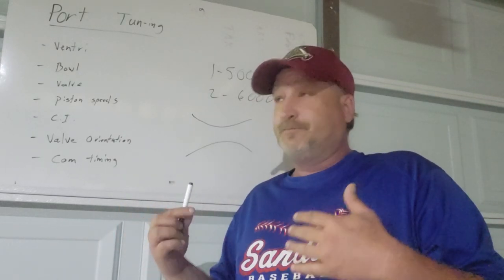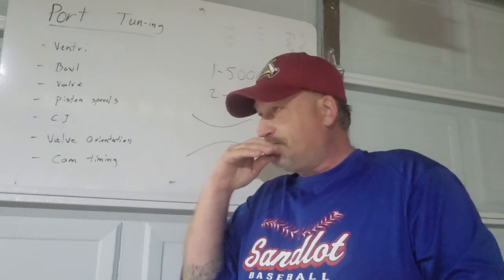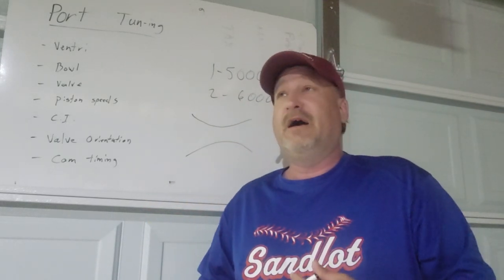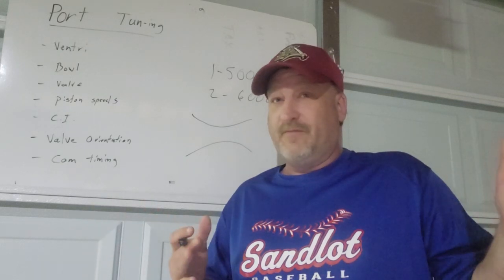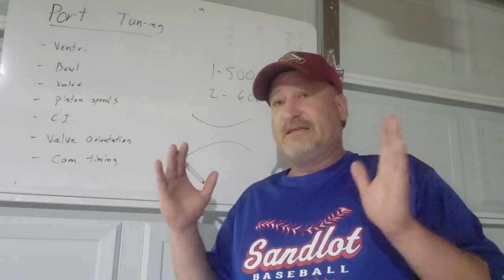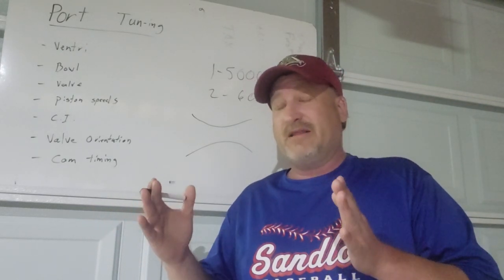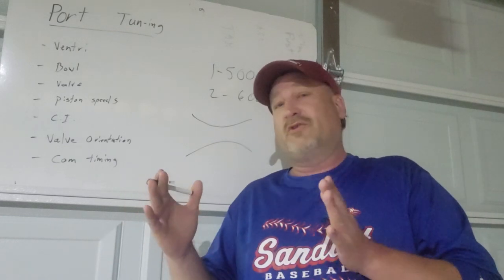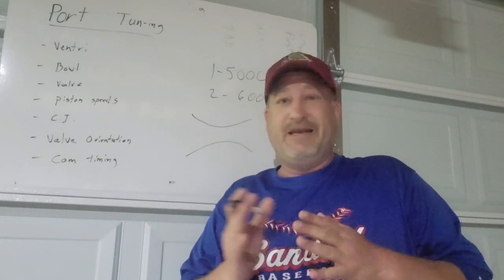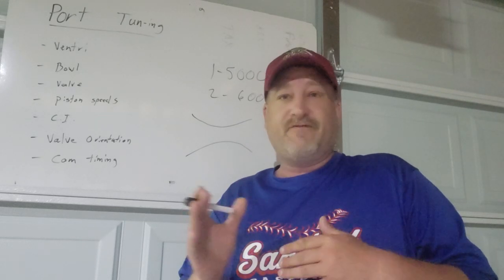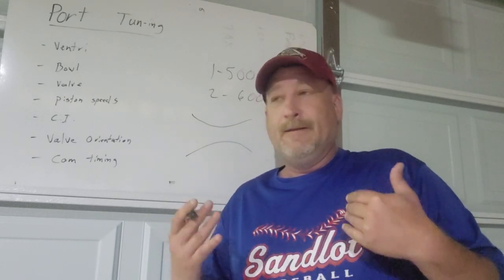So again, going back to the small block Chevy, most of your engine combinations, whether it be from Ford or Chrysler, they stuck to a certain connecting rod length, and they may have altered the stroke of the engine to mitigate or to shift around the cubic inch.